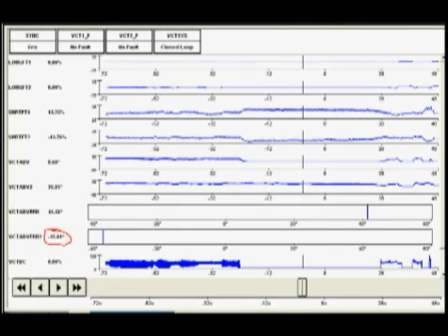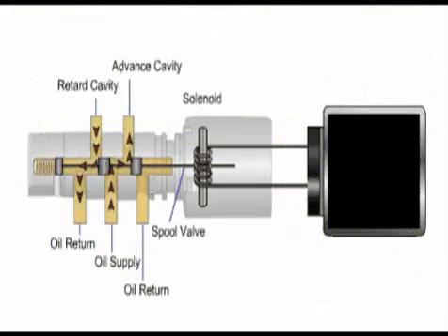Now later on, after letting it get hotter and hotter, both cams will end up being retarded. The problem is that the PCM is relying on bad information for the correct position of the cam, and therefore producing an error for both cams. So now the question is, what would make a cam stick retarded, but then occasionally not do so?